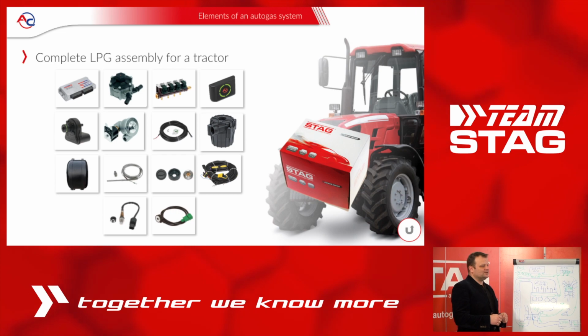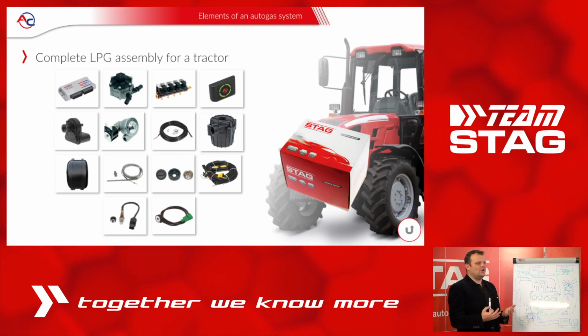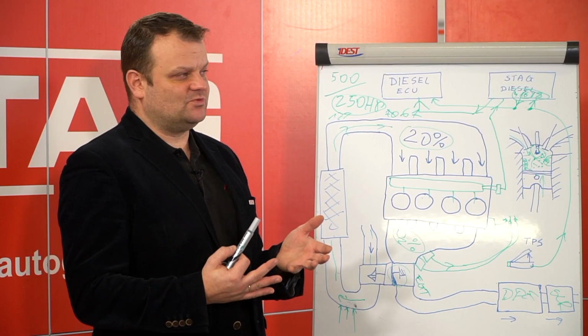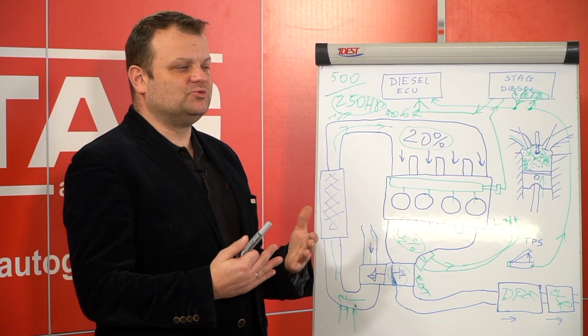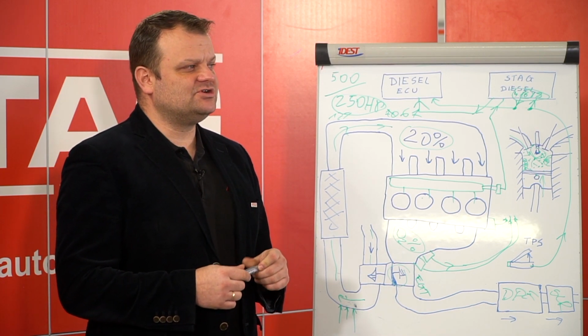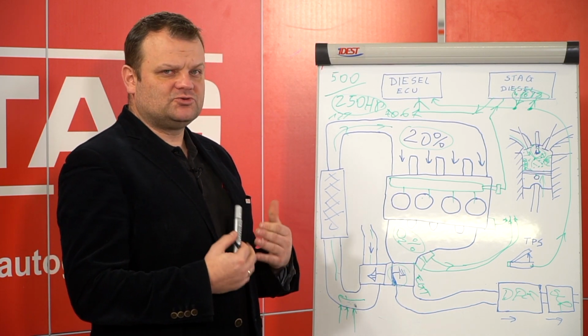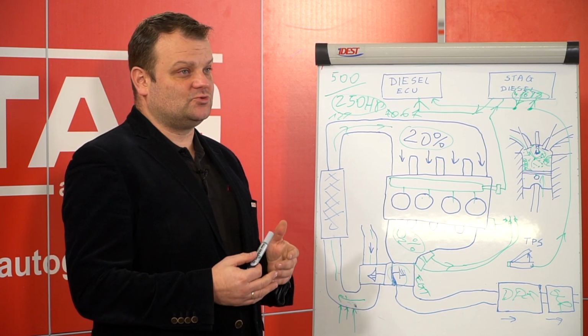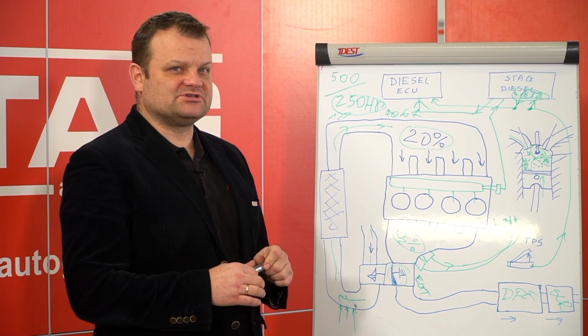Yes, a lower power tractor can, for example, handle machines of 2 or 3 tons maximum, because its output power is the limitation. But with the CNG or LPG system, the output power is 20 or sometimes 30% higher.